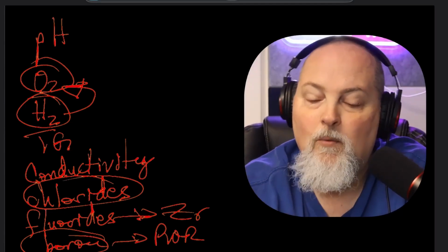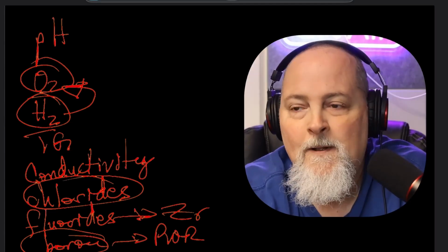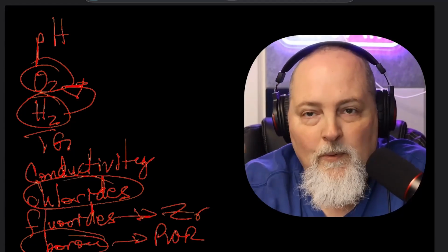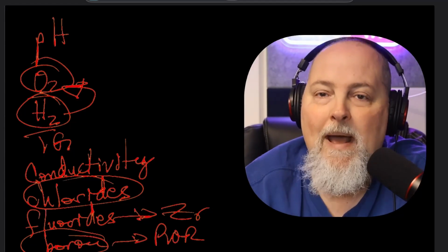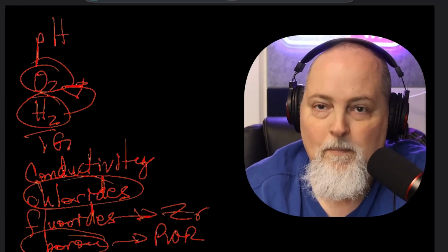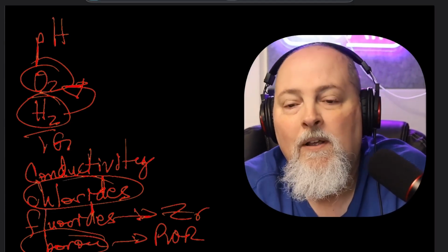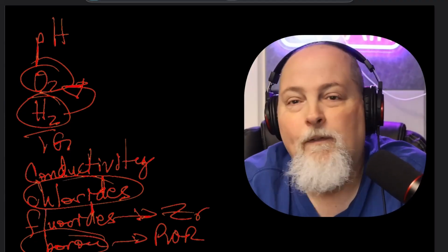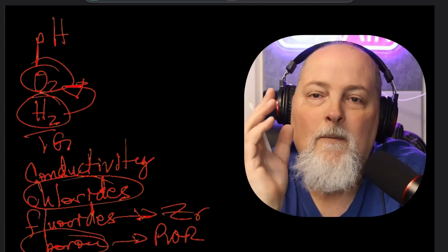What if they don't? Well, we have a mode switch, and we rotate that mode switch, and it's an informal backup reactor protection. We rotate the mode switch. Rods should go in. What if they don't? We have a backup scram, and so we push the alternate or backup scram valves, and we hopefully put the rods in. What if they don't? What if all our methods of trying to get the control rods in to shut down the reactor don't work? We inject boron.